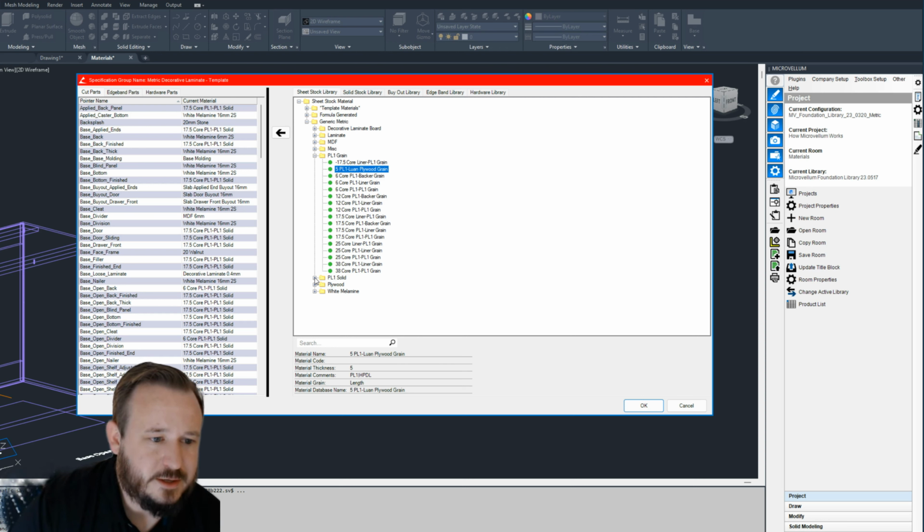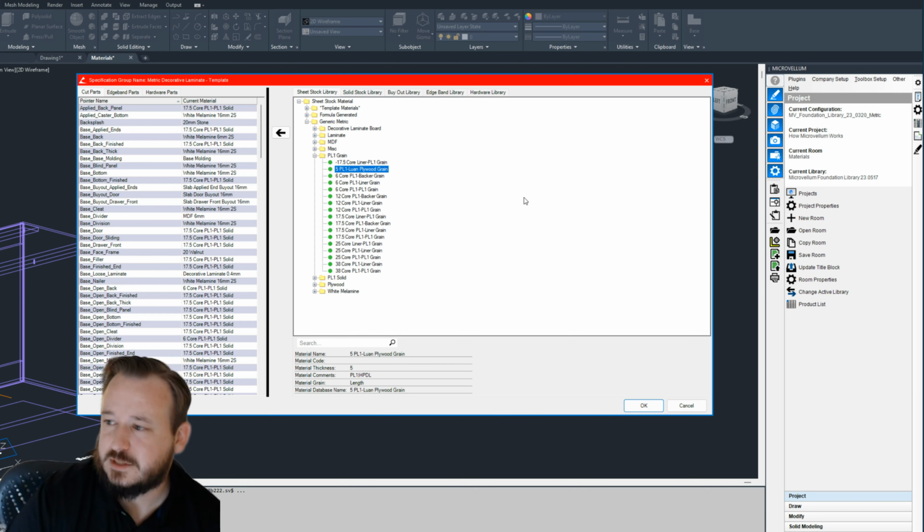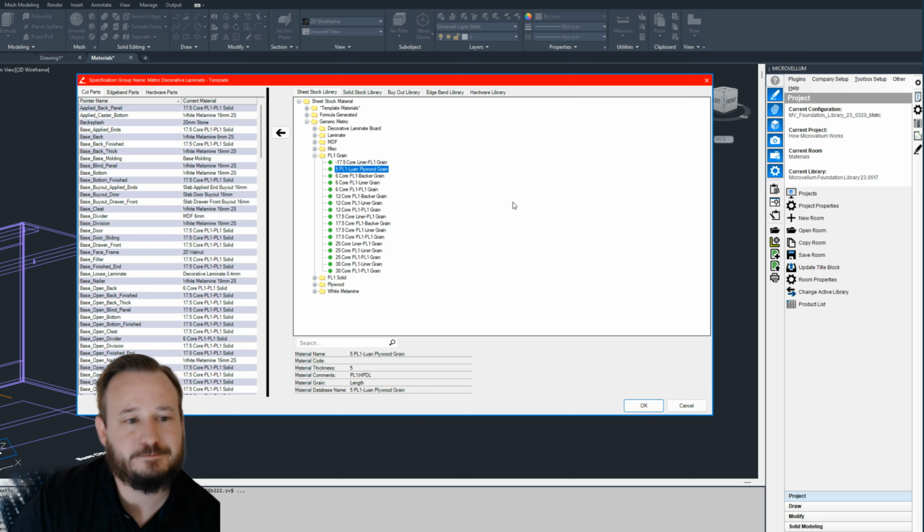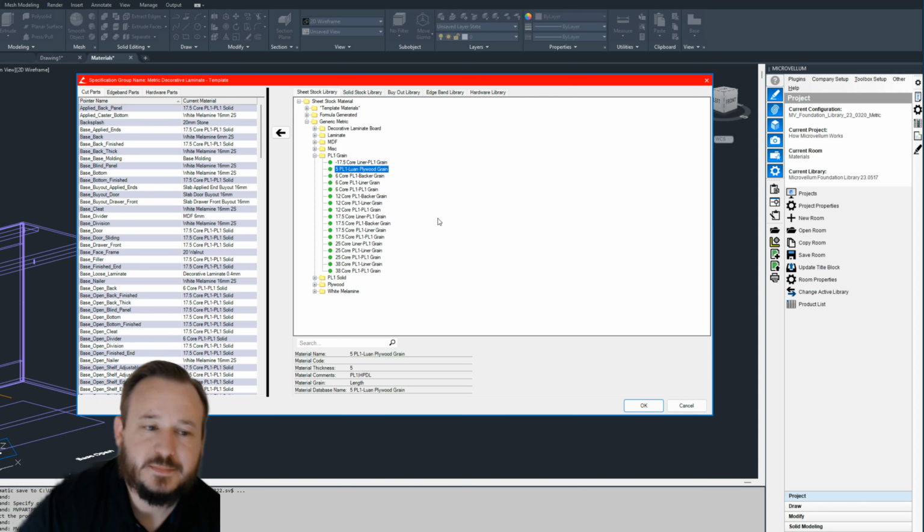And none of these are clonable yet, but why would I want a clonable material? As I mentioned before, a lot of the time you may always want to be able to edit the thickness and sheet sizes of your materials in your projects. Because you can find and replace the description and rename descriptions of non-clonable library level materials, but nothing else, you can't edit the thickness of those.